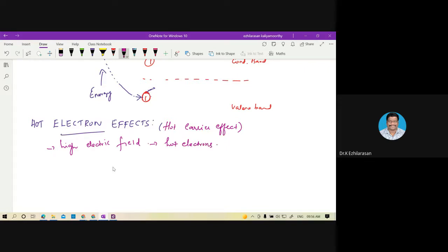Those high energy electrons can enter the oxide where they can be trapped, giving rise to oxide charging that can accumulate with time and degrade the device performance by increasing the threshold voltage, and it will affect the gate control on the drain current.